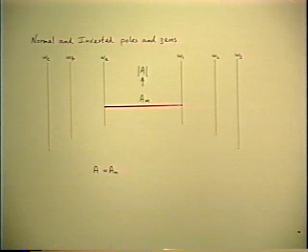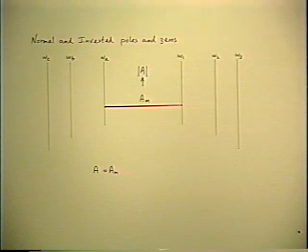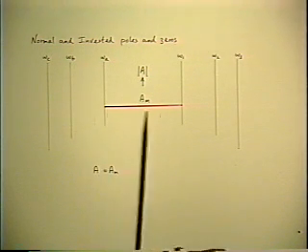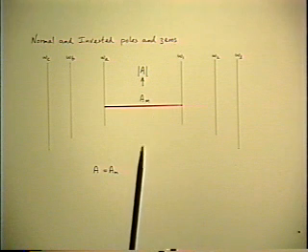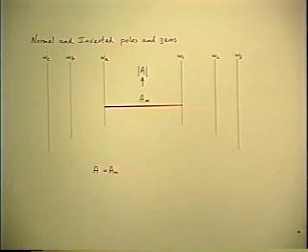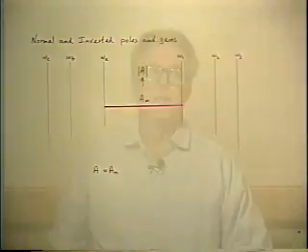There's a flat gain. Called it a mid-band gain again, just for simplicity. What I'm going to be emphasizing now is the relationship between the asymptote sketches and the factored pole zero forms. Because probably what you're used to doing is doing the algebra, getting the equation, finding the poles and zeros, and then drawing the sketch. What I want to emphasize now is the reverse process.